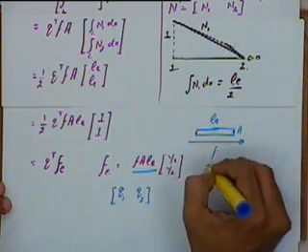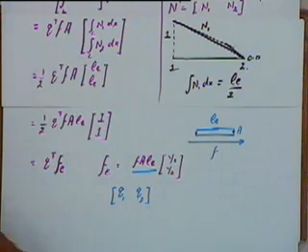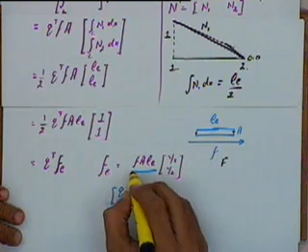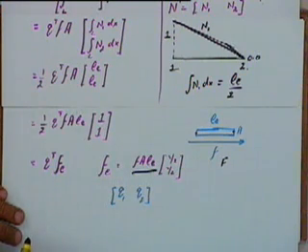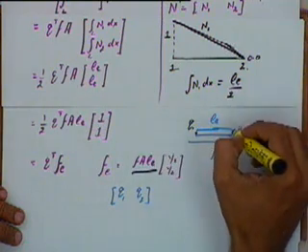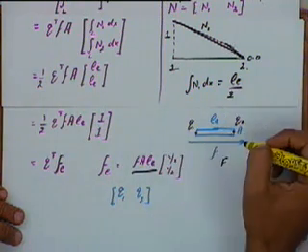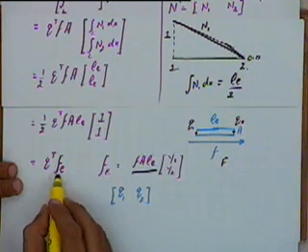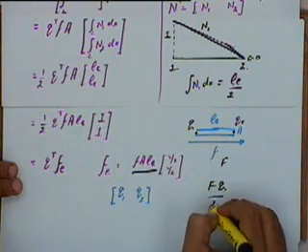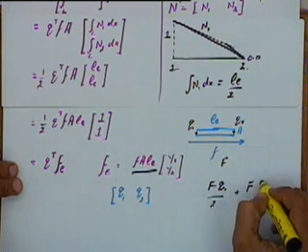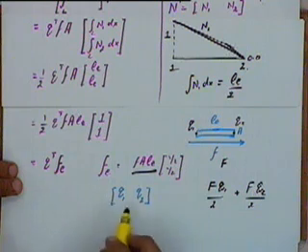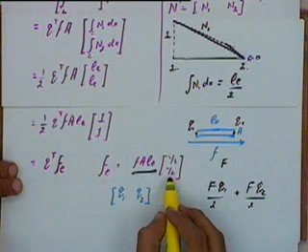The total force acting on this is, let's say, F. That is this term. So the deformation here is Q1, deformation here is Q2. I am saying that this potential energy is equal to F into Q1 by 2 plus F into Q2 by 2. That is what this multiplied by this will give us.